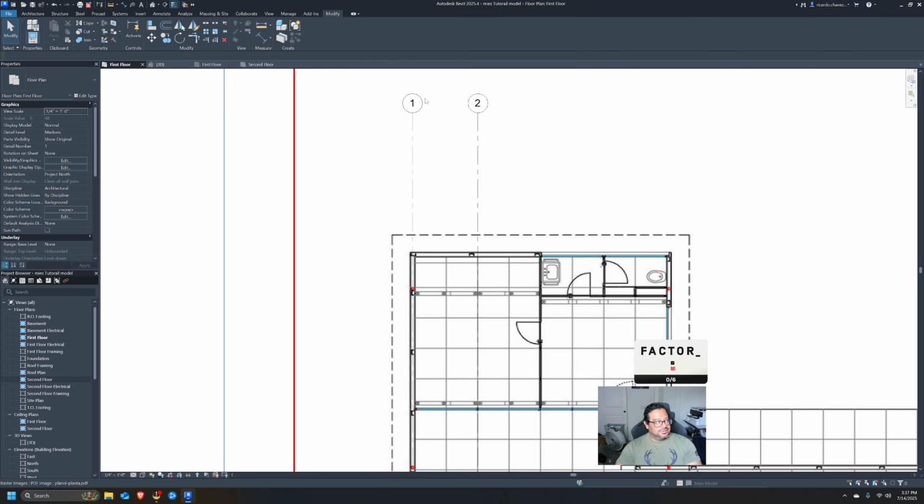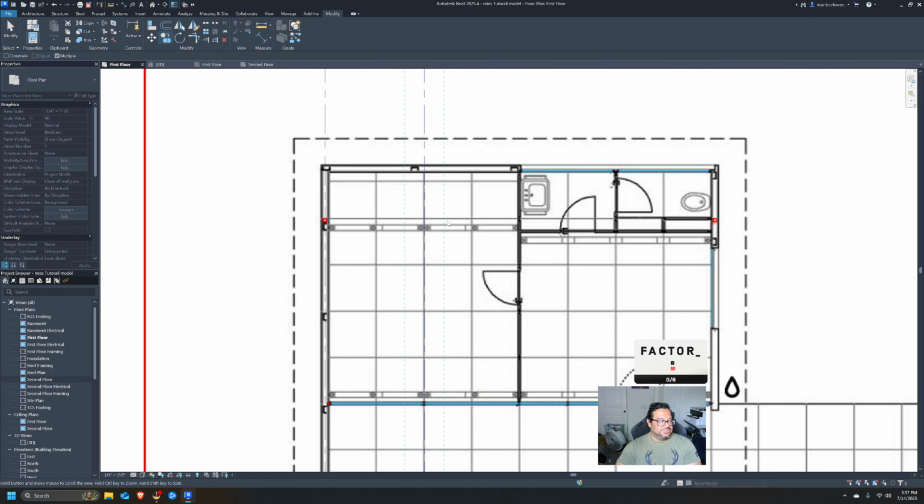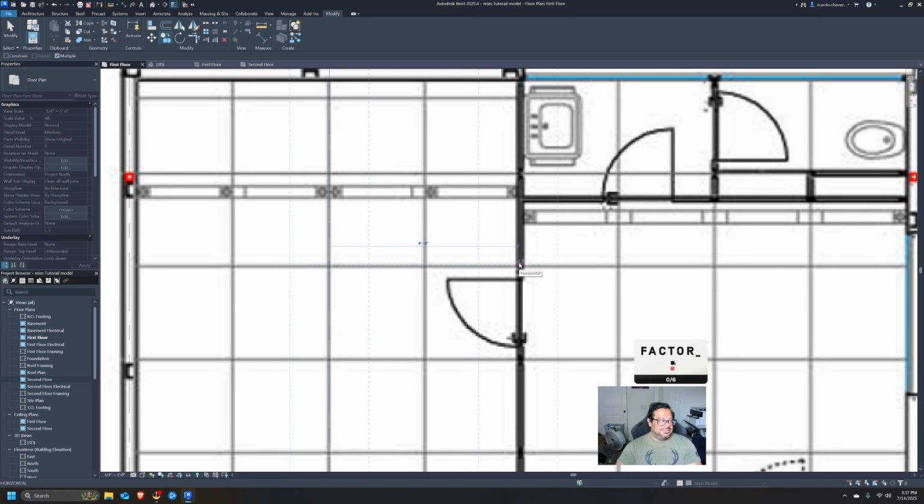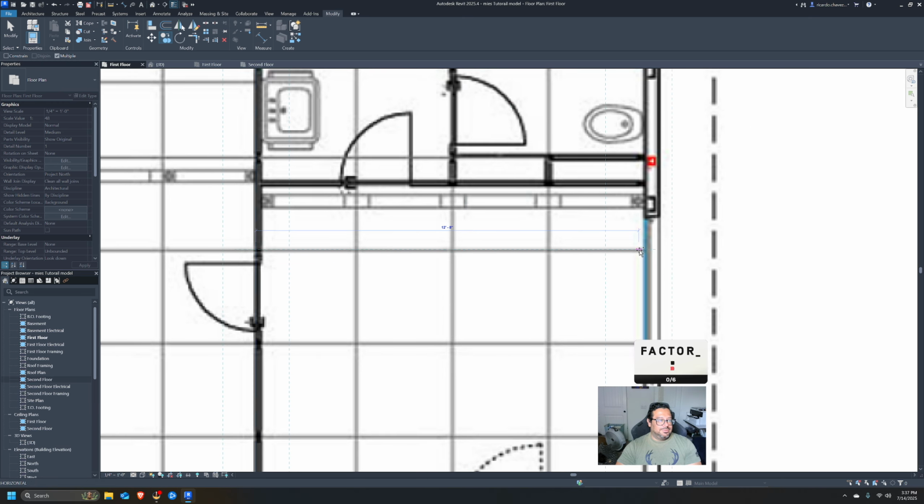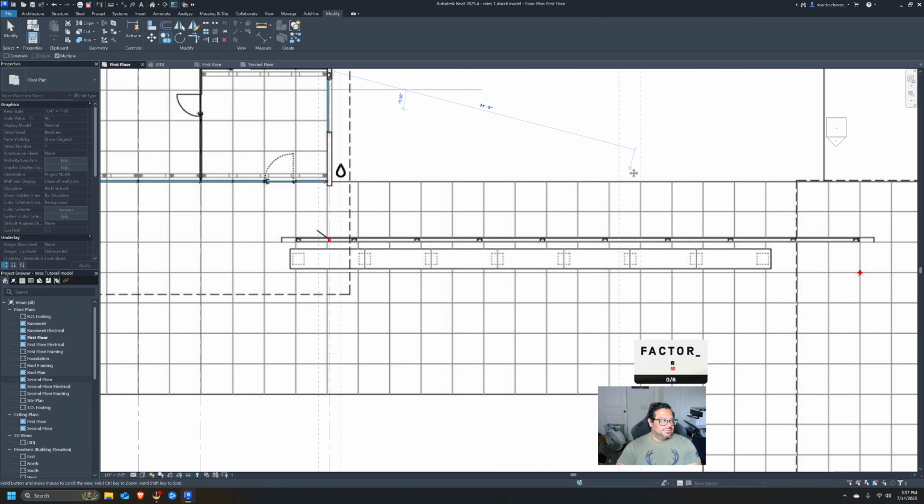You can go to Modify. This is your copy. Click on that. You're going to click on your object. Click spacebar. You can click Multiples and Constrain. So we just click on any edge. We'll bring it here. You can see we're going to click 6.3. And then it'll keep going, so you can keep going because we hit Multiples, and then we'll click.